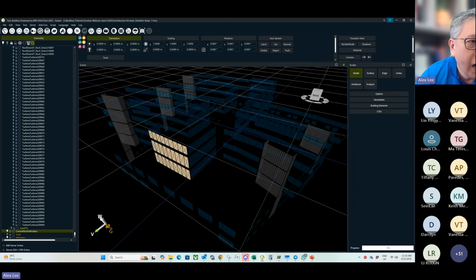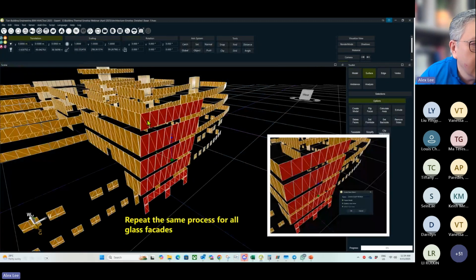Now, I just highlight to you that for one particular facing of the glass panel, after the separation, this is what you will get. If I zoom in on this group of glass, you realize that, as a BIM modeler, you know what I'm talking about. The glass that you have selected is not just one surface, because the glass is a solid element, a solid model, so it contains 6 patches. One facing north, forward facing, backward facing, left, right, top, and bottom.